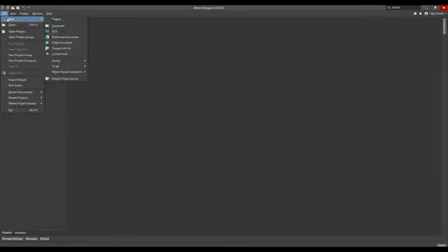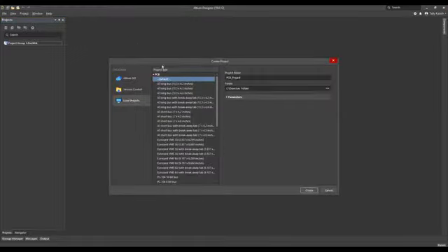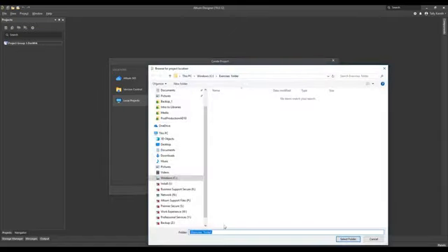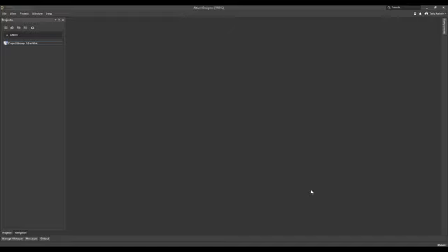Let's start with a new project. To create a blank project, click File, New Project. This enables the Create Project window to pop up. While there are many options here, we will start with the typical PCB project with the default PCB. Here we can name the project and determine where it is saved, as well as if we want to create a folder for this project to be saved into. We will call the project Expansion Board and have AD create a subfolder under the Exercises folder by selecting Create.